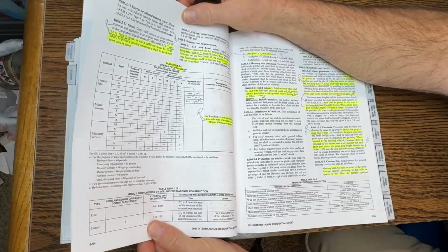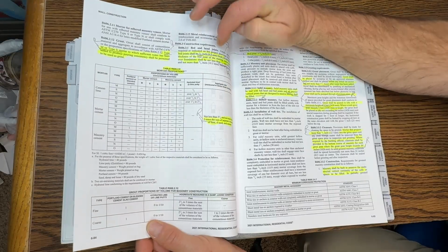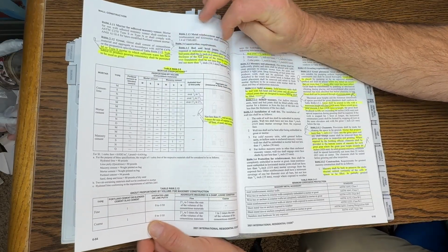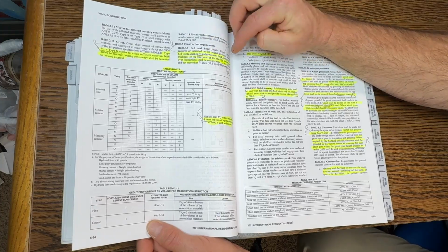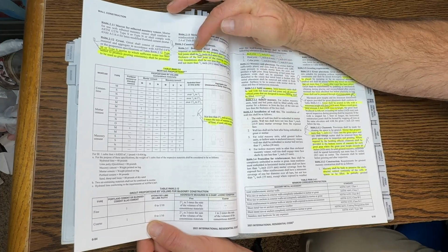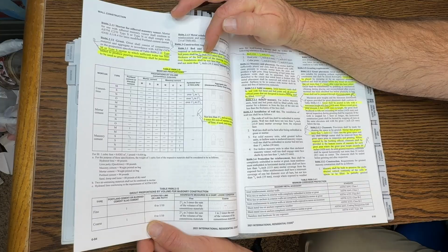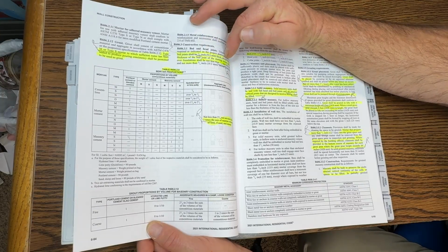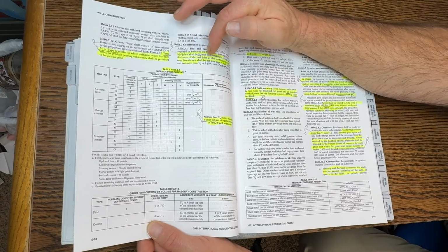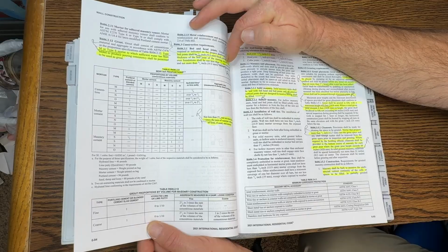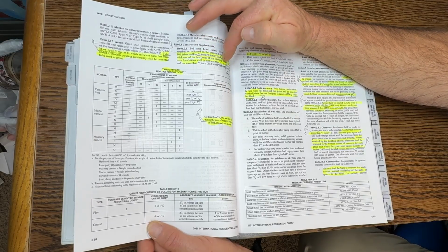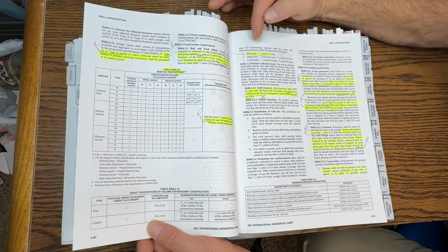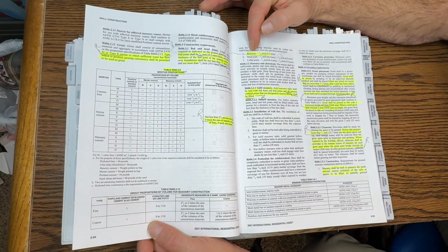R606.3.1, and we are right here. So I'm going to read this whole thing because it answers a couple of questions that we're about to look at. Unless otherwise required or indicated on the project drawings, head and bed joints shall be 3/8 inch thick, except that the thickness of the bed joint of the starting course placed over foundations shall be not less than 1/4 inch. Now I want to point something out, because we're going to ask this here shortly.